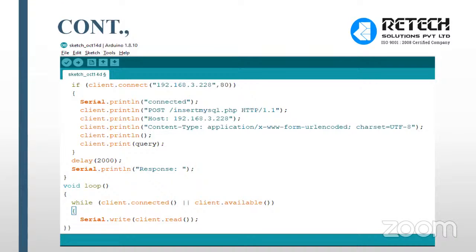Now I will tell how to read the sensor data from the controller. For every controller, whether you are using Arduino or ESP8266, it is the same program. But Arduino has lots of analog to digital converter pins, while ESP8266 has only one analog to digital converter. If you want to read two or more analog sensor pins, you definitely need the MCP3008 external ADC IC. Now I will tell how to read the sensor data in the Arduino IDE software.